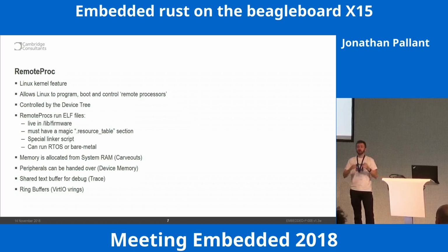You can hand over memory-mapped peripherals. You can say, UART3 is at this address. I'm going to give UART3 to my Cortex-M4. It has full control over this peripheral. Linux is going to ignore it. If you do that, remember to delete UART3 from the device tree. Otherwise, both Linux and your embedded processor are trying to write to the same peripheral at the same time. You're going to have a bad time debugging.